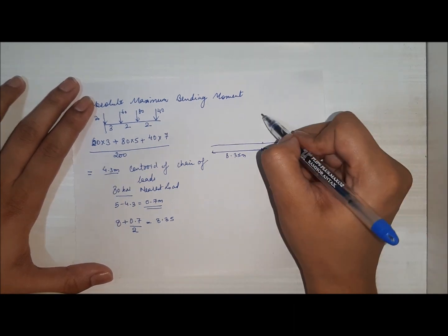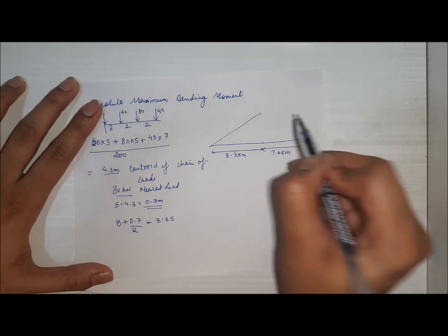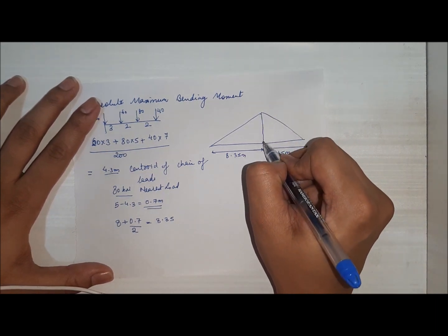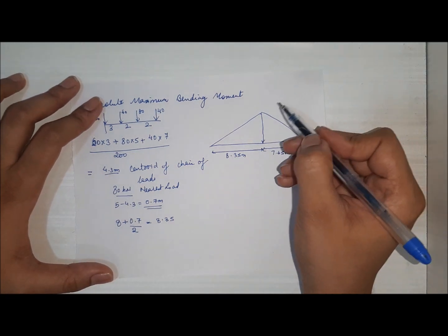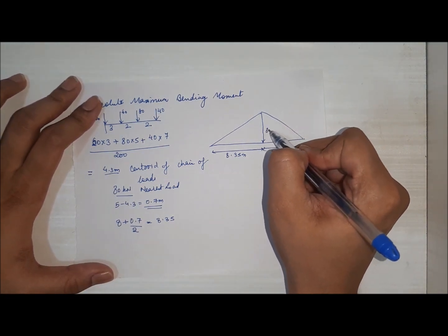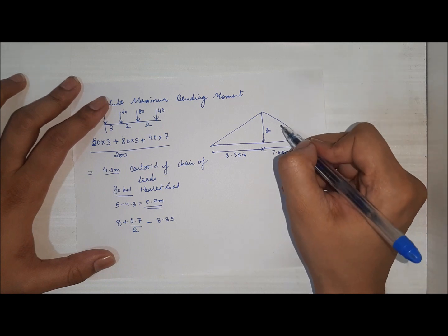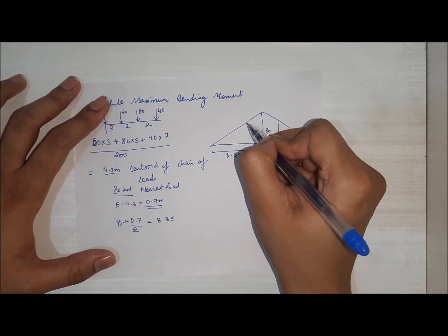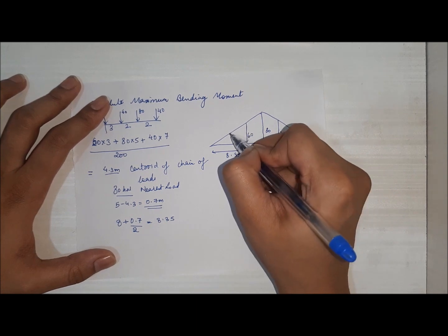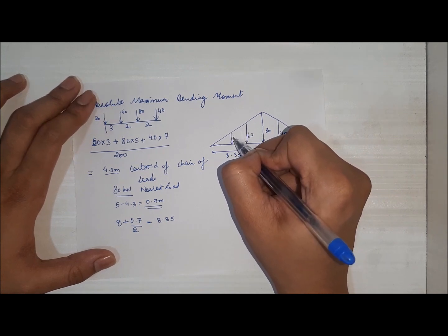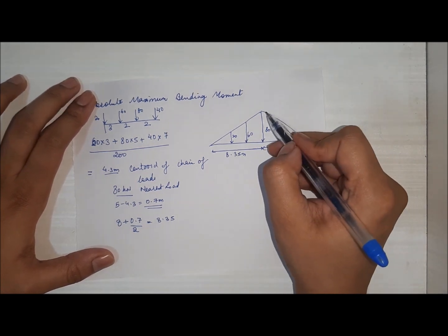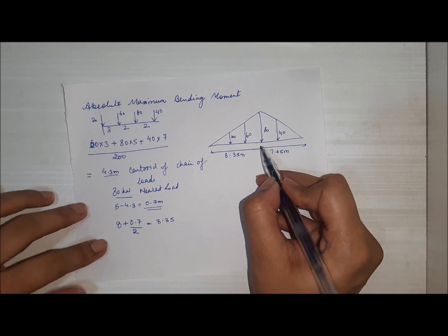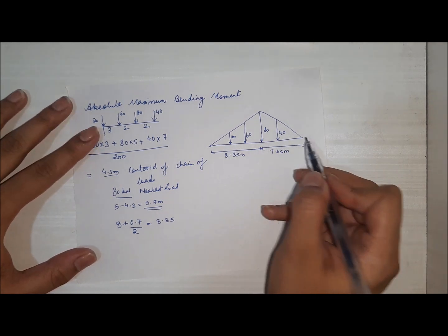At this point we will get the maximum height. So the load that is nearest to the center of the chain of loads is the 80 kilonewton load. Here 80 will come, then here we will get 40, here we will get 60, and the last load we have is 20. Now the height will be 8.35 into 7.65 whole upon 16.